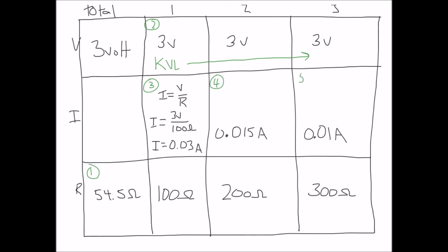Okay, so after we found all the currents in all these places, the next step, and in this case our last step, is to find the total current. Now, we know that there's something called Kirchhoff's current law, which basically says, in fact, let me go back to my picture. What this means for us is that when we take a look at the current in all of these 3 resistors, if we add them together, we get the total current for the actual circuit as well.